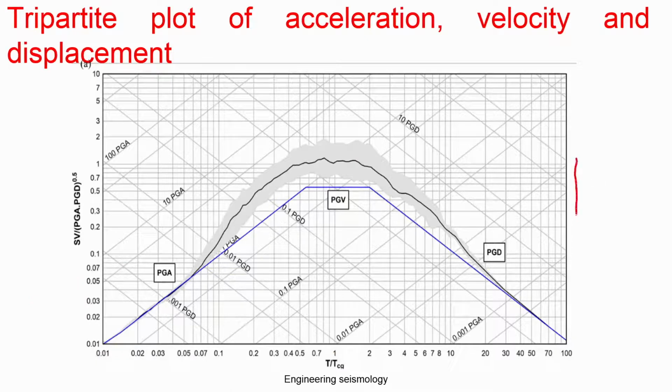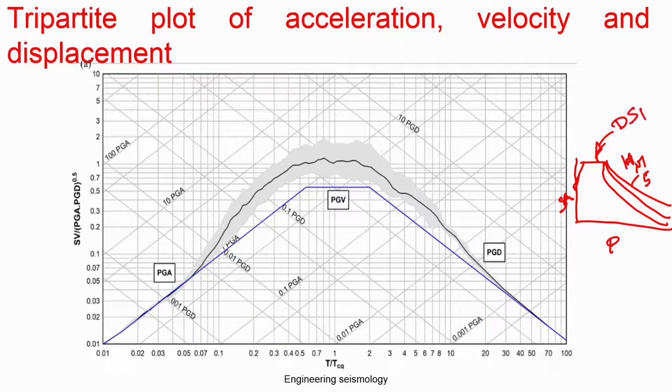This design spectrum is basically period versus spectral acceleration, and then they give some shape. This is basically the Indian design spectrum, which has 3 divisions, for hard rock, medium soil and soft soil. Okay. So, dense or hard rock, medium, and soft soil classification. This is the period, this is the SA. So, this is basically a design spectrum. Okay. As we have seen, the low period is acceleration, this is the velocity,